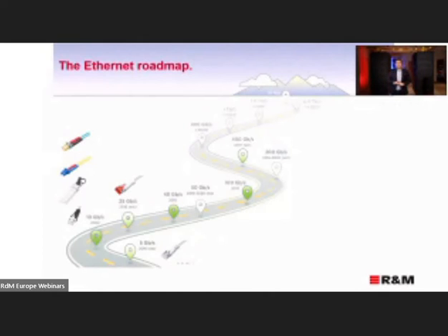We also checked with our products, and we can give the warranty to the end user that our module category 6A ISO installed on cable category 7A will give performance good enough to run 25 gigabits, but for a shorter distance, not for 100 meters, but for 25 meters. But for the server room, for the data center, a distance of 25 or 30 meters in the channel is enough.